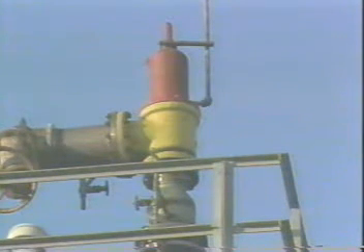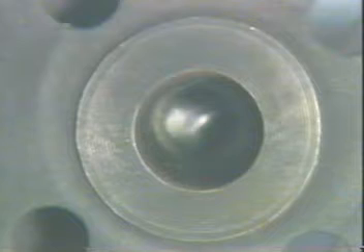Thermal expansion of valve components may also pose a problem with ball valves. For example, when this type of valve shuts, liquid is trapped in the ball. To prevent damage by thermal expansion of the liquid, the valve must be designed with a suitable vent hole or with a valve seat that relieves internal pressure buildup.